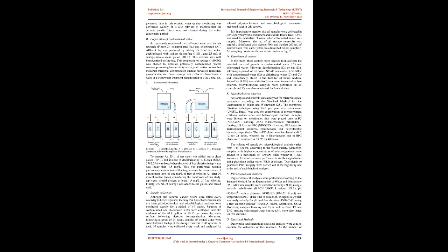Moreover, the tap of all storage reservoirs was carefully disinfected with alcohol 70% and the first 200 ml of treated water from each system was discarded before sampling. All sampling points are shown within circles in Fig 2.